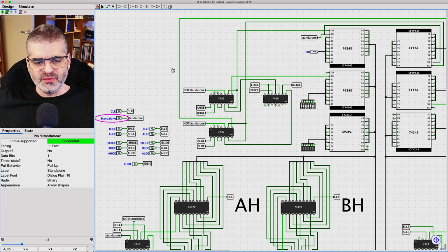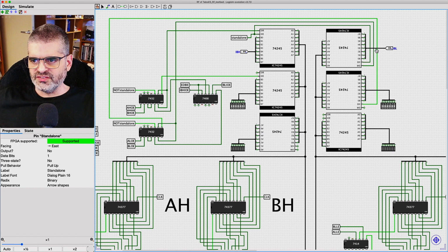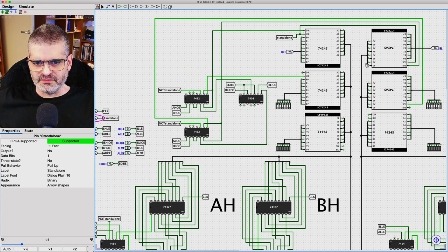But the direction is important. Right now, all the other control bits are disabled. Let's look at the direction. The direction is dark green, so that means it's ground. That means it's from B to A. So it takes the internal bus high off this card and connects it into the local bus high. And on the other side, the same thing. It takes the internal bus low, the signals that come from the backplane connector, and drives them into the local bus low, because the output enable is active.